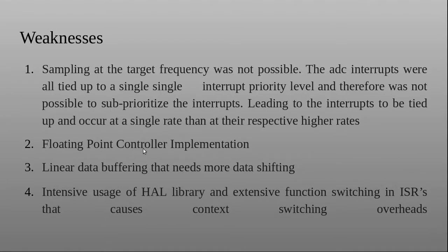Also, the floating point controller implemented here is processor intensive, and the controller was implemented with a linear data buffer that needs more data shifts than a circular buffer, which we'll talk about in the next slide, which is a better application. There is also intensive usage of the HAL library provided by STM. Though it's good for real-time operating system interfacing in the long run, it can take up a lot of context switching overhead, and it's not the most ideal thing there is.